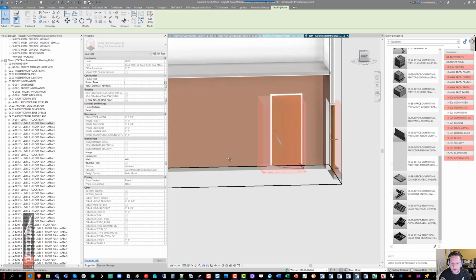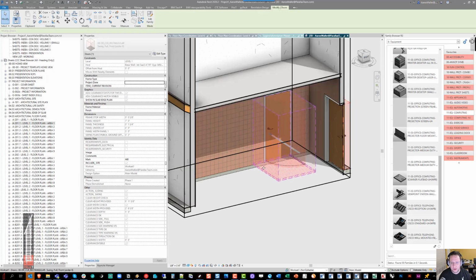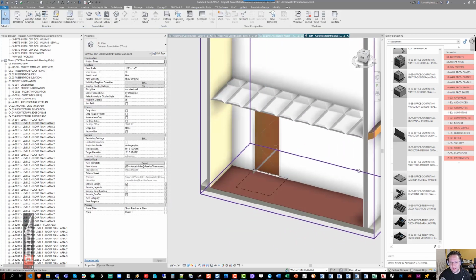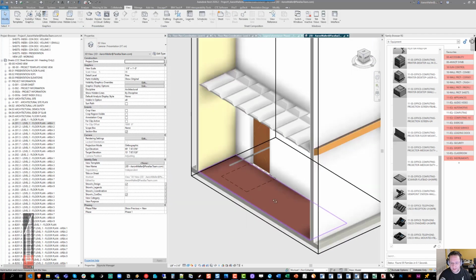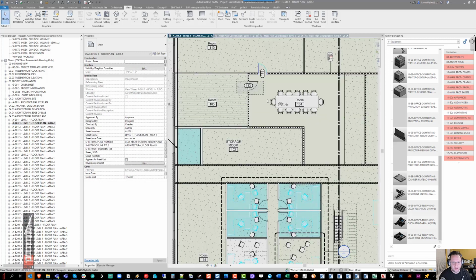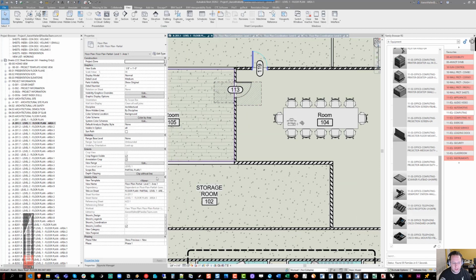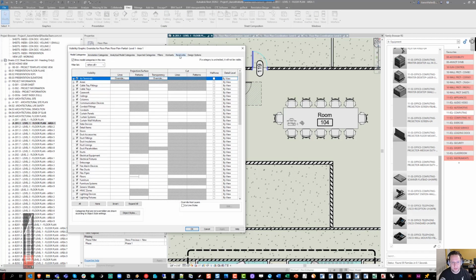These are all shared nested families, and that filter is simply turning them all transparent so that we can see through them in plan. This is important because if we couldn't see through them in plan, there would be a solid box here which would obscure the rest of the documentation. So the clearances all categories filter is turning all categories clearances transparent.